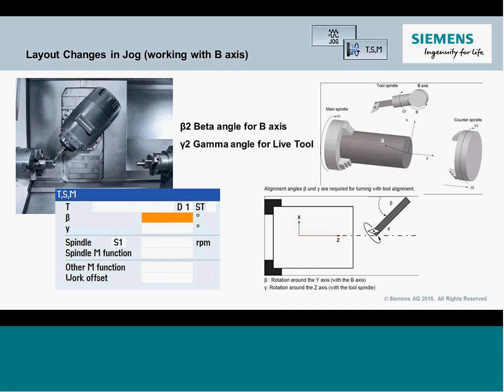Imagine, or if we reference the right side image, I have a turning tool and I want to orient it and then move it around in space. Certainly I can swing the B-axis with the beta field, 0 again, which is at 9 o'clock, swing it down, and use the gamma, which is the orientation of the spindle, to flip it around. In my right-hand view, that right-hand turning tool, if I want to cut the outside of the part, I leave it at some angle, probably 45 degrees or less, could be 0. And my gamma orientation, or my spindle, is 0.